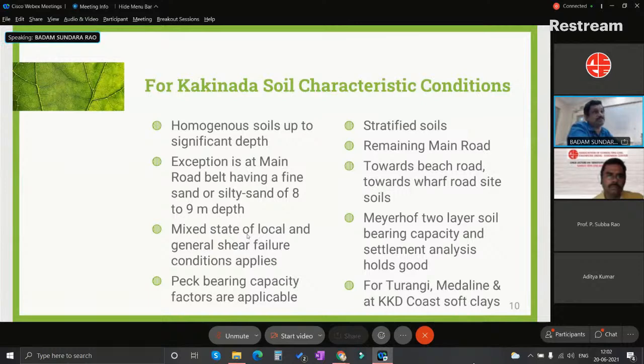Why I am emphasizing this is that it depends upon the soil stratification. You have to select the appropriate bearing capacities. Then only does the geotechnical investigation report, the SBC or the SBP, what we finally say in terms of the allowable bearing pressure, have significance, reality, or sensitivity, we can call it. Why? Because once you adopt a wrong approach in the bearing capacity factors, that leads to an entirely different solution, which is not practical and is not real either.